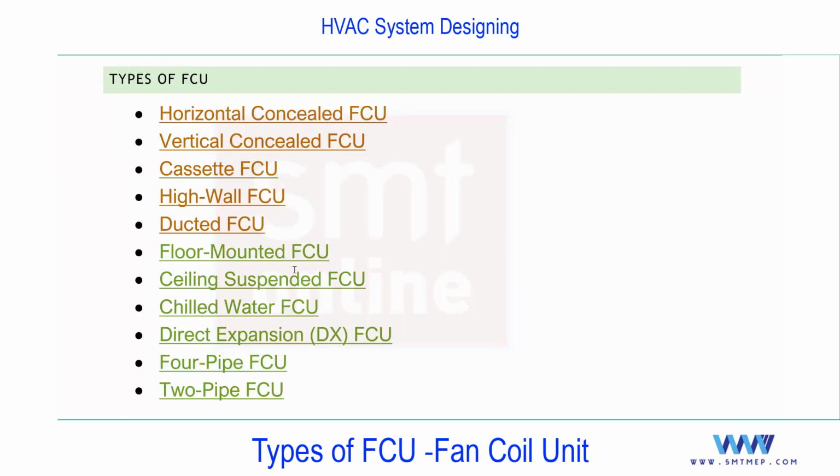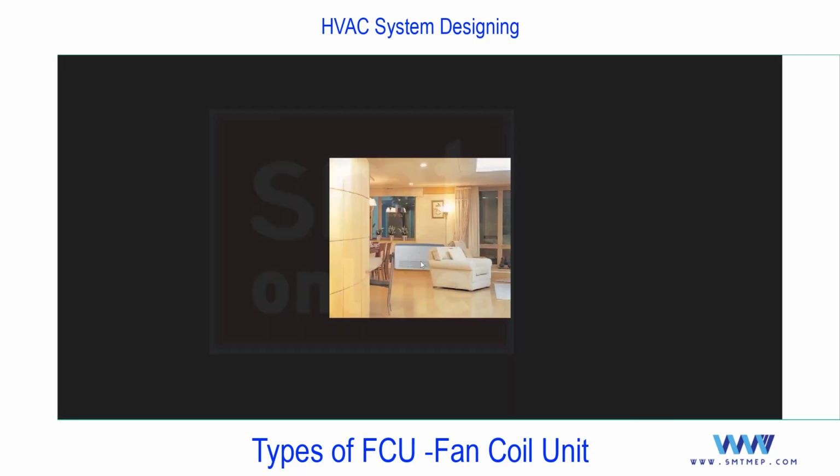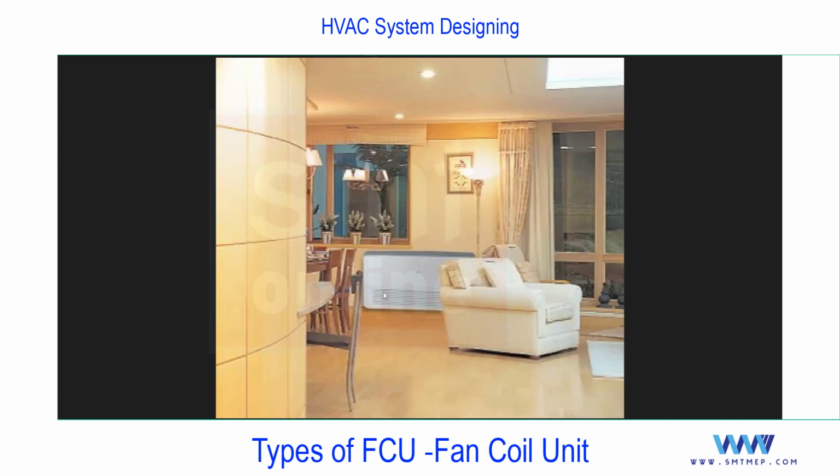Next, we have a floor mounted FCU. This is a decorative type. This is also not commonly used. You see, very rare, with a few models only. And technically also, it is not at all recommended to supply the air from the low levels because cool air is dense. In case of heating, this is a good option because hot air density is less. If you supply from the floor level, as the density is lower, it can go up and heat the room. But this is not at all recommended for cooling purposes. But anyhow, it's an option available in the market, and as per the requirement one can use it.